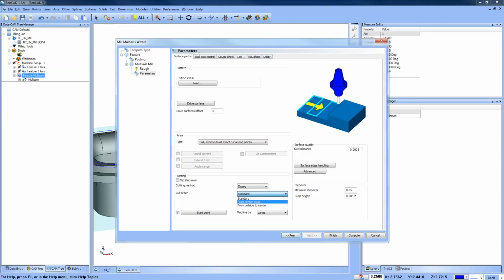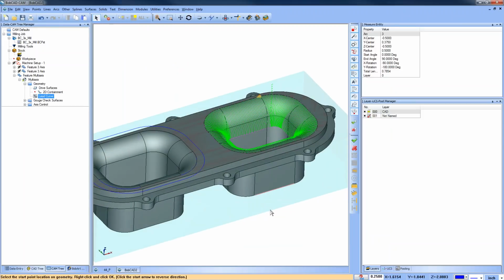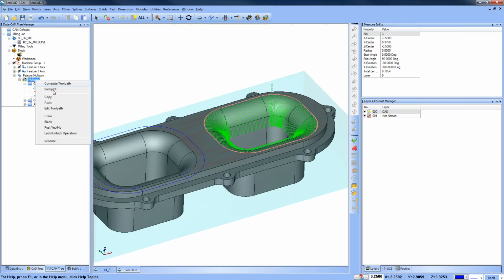and not get stuck on it, because if you spend too much time getting stuck on a feature, then you really do lose production. This one here, if I needed it to move, let me see if there are some other options. We have our lead curve, and then we have a modify start. So in this case, instead of it being from the start point within the toolpath, my assumption is it's going to change based off of this start position here. So I'm going to move the arrow over there. We'll hit our space bar. Let's recompute it, and let's see if that makes me right.